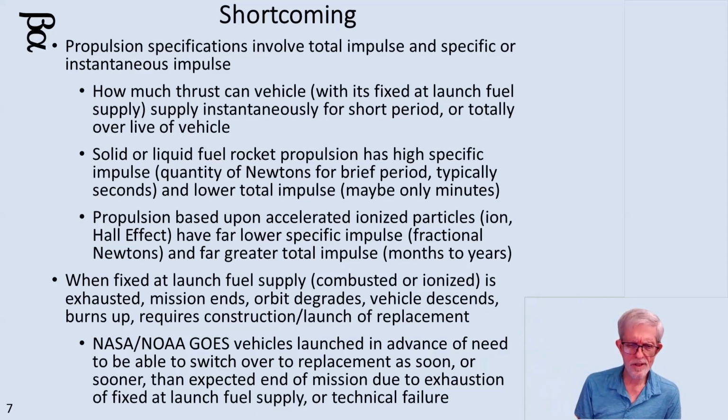But you also know that there are deep space probes that have lasted for years. They're ion propulsion, and what they do is they run at about 11 to 14% of total thrust output for months at a time, and it adds up. This is how they go faster and faster and faster. And then when they get into orbit of something, they have to use their chemical rocket because it has a higher peak thrust to quickly slow the vehicle down to go into orbit. And then when they want to leave orbit, they use the fuel to kick it out of orbit, and then they use the ion thruster to take it to its next location.